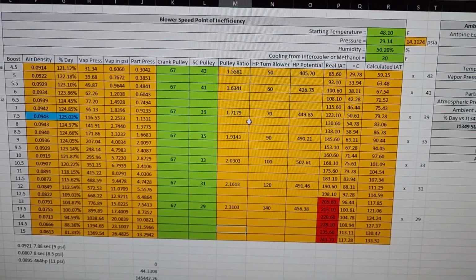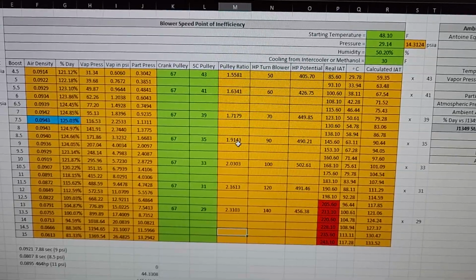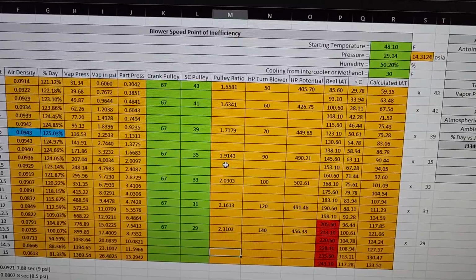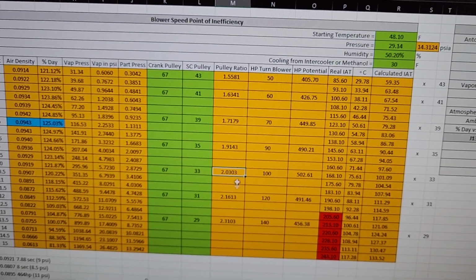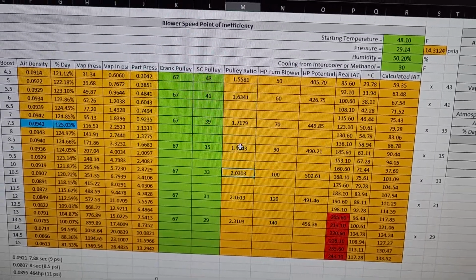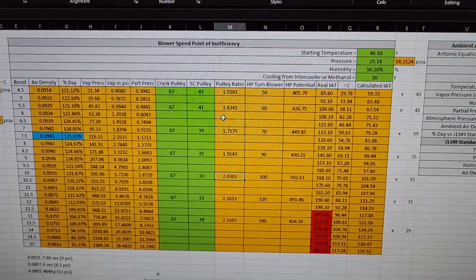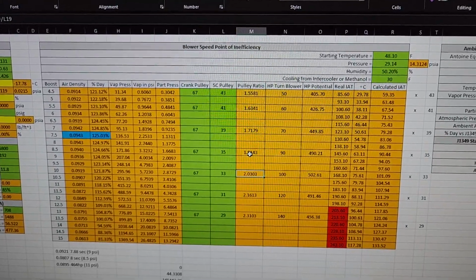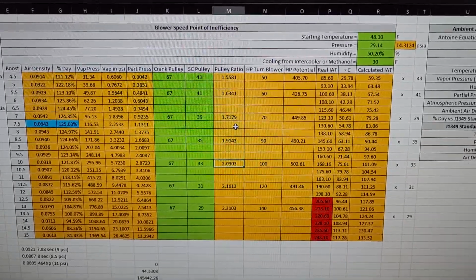Okay. They're going to be similar horsepowers to turn blowers at similar ratios, but when you start getting into 671s, 871s, 1471s, they're going to take more horsepower to turn at the various blower speeds. You don't spin a 671 at 2 times. Usually you kind of max those things out at like 20% overdriven. You get beyond that, you start really pumping some heat in. But again, that depends on application, and that's kind of a general rule of thumb and not absolute. So anyway,